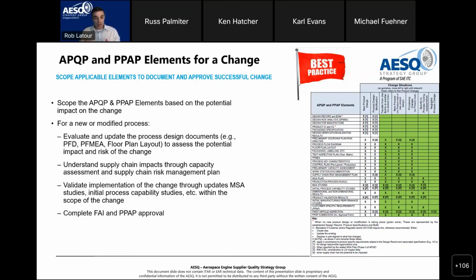Right. So, bottom line messaging in all this, first with any change situation, we need to have a kickoff with good planning up front, right? Quality planning, APQP is about planning. So lay out the plan, look at what phases are applicable, how do we need to configure those phases. Based on that, we can set our waypoints with the APQP events, set our timing plan for the change, and configure those events to match the scope of the change, and then execute our elements.